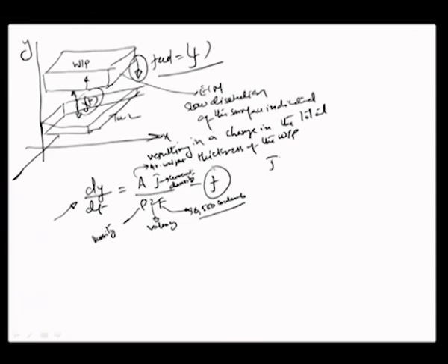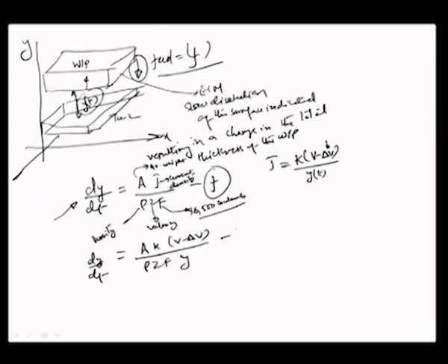And then, if you substitute the formulation for the current density, which is also represented as the conductivity of the solution times the available voltage, V minus delta V, where delta V is the overvoltage potential which has to be given in the design voltage so that the amount of machining that you intend takes place, divided by y, where y is the gap. So this expression amounts to dy by dt equals A times J divided by rho Z F, over y, minus f.